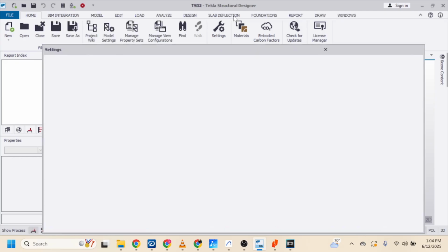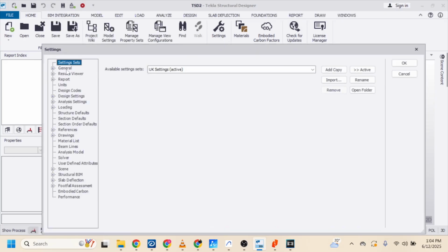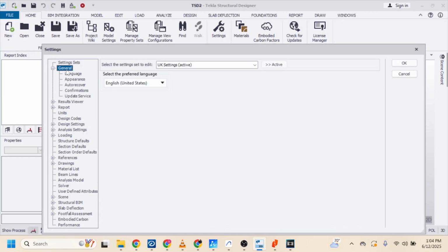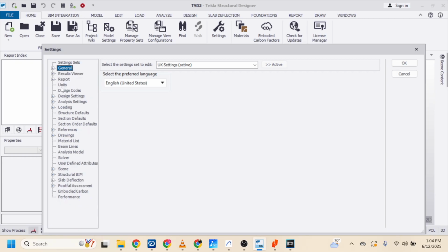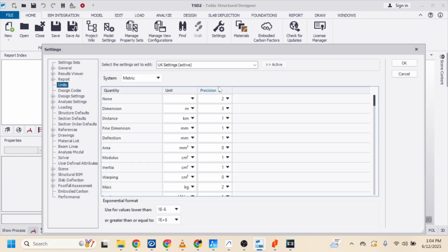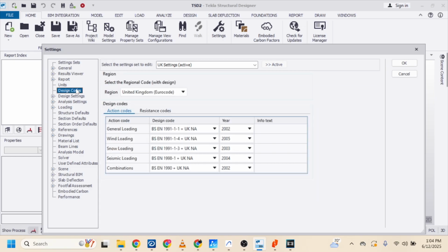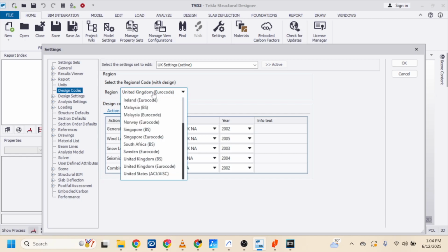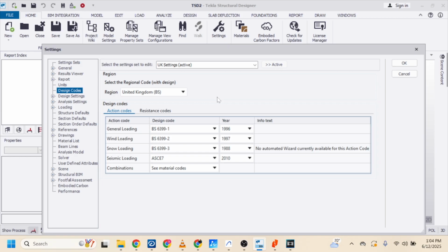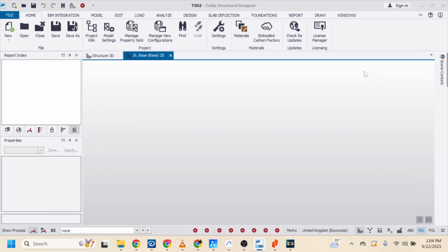For this, we'll use typical beam dimensions like 200 by 450 mm, which can be adjusted later depending on design requirements. After setting up the beam framework, we'll proceed to model the slabs. These will be cast in place and designed later based on span conditions. We'll use the slab panel tool and define the thickness as 150 mm, drawing the panels between the supporting beams. Tekla makes it easy to ensure proper snapping and alignment, so the slabs are connected seamlessly to the beams.